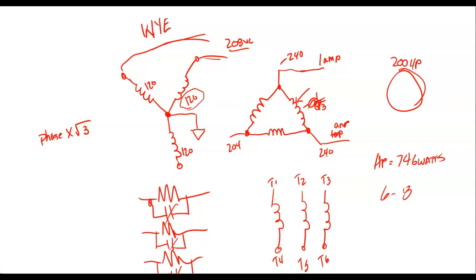So what happens is we would have a relay. Instead of using resistors, when they're dropping all that voltage, they get real hot, and that's just wasted energy. What we'd like to do is have a way that we could just reduce the voltage at the motor without using resistors. So what they do is they have a circuit out there, and they start it Y, and when the motor gets running, they'll switch it delta, and then they get the full voltage. So these are what we call reduced voltage starters.